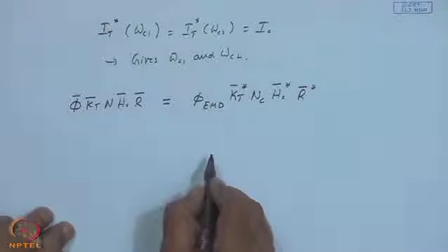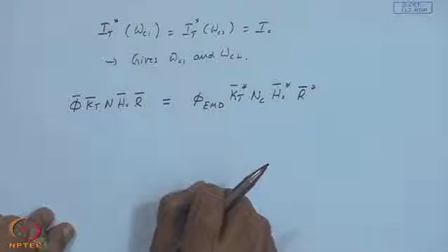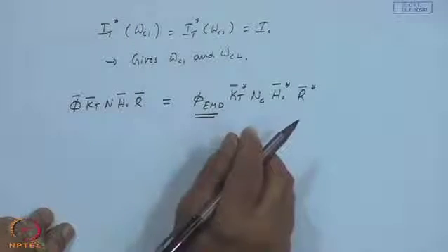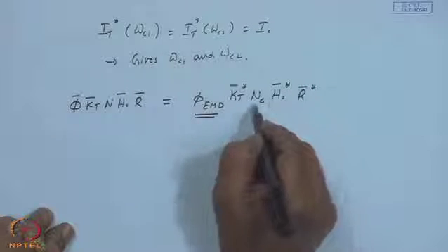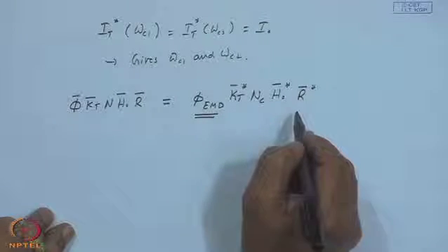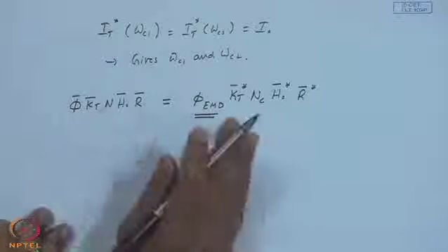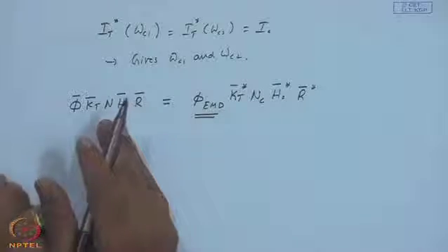What we realized is the solar radiation available above the critical level, whether be it based upon the equivalent mean day of the average days with KT greater than KT minimum, or all the days with the monthly average daily utilizability phi bar with corresponding n, should be equal, because the other days are always less than the critical level and they do not contribute to any solar radiation falling on the collector surface above the critical level.